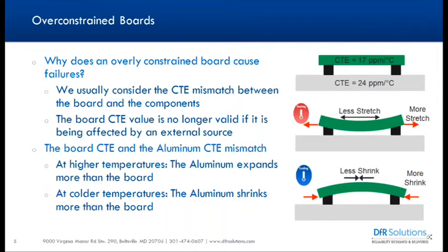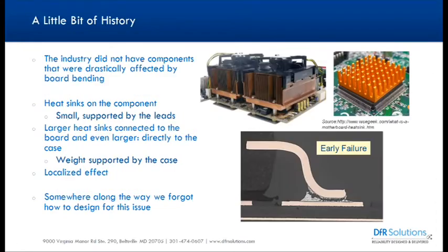One of the other things that happens is we kind of forget that when we connect the board to the heatsink or to the case or to the housing, we're usually doing this at room temperature. If we do a hard contact between them, then when it shrinks, the board is subjected to a compressive load from the case, and it'll buckle like a beam. And that one can sometimes be worse than the effect of when you stretch the board. So let me go back a little bit into history of how we got to this place.